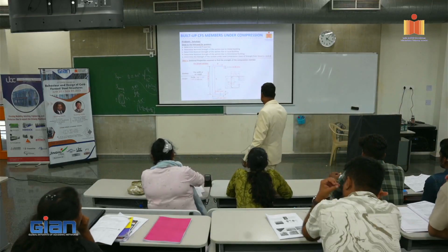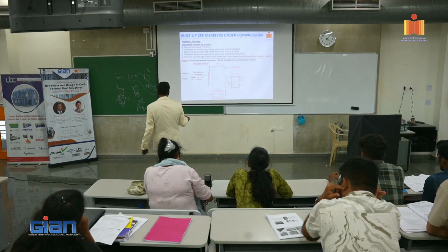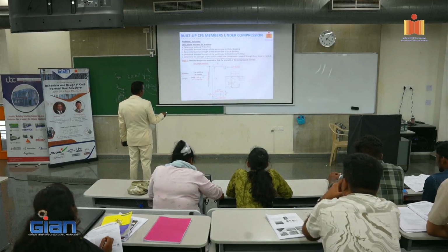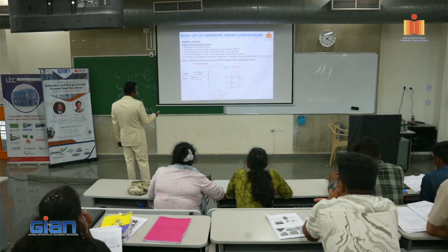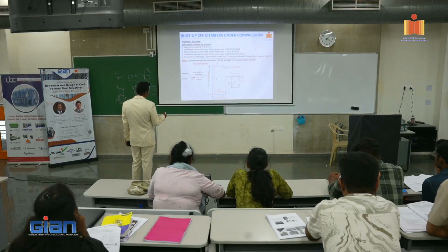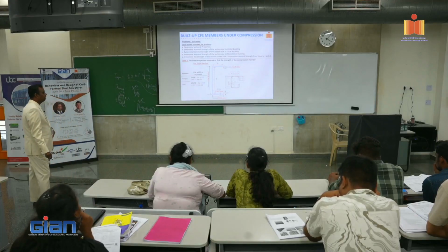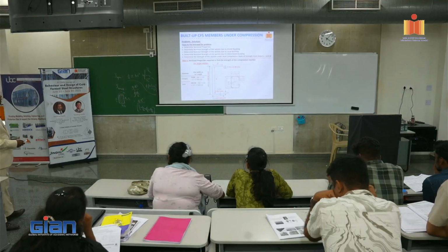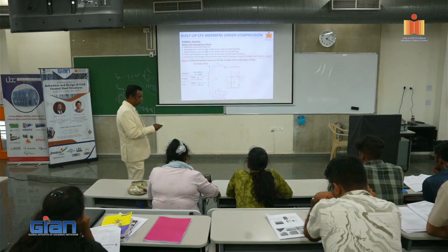So the flange is 74.96, we have 2, right? R plus T by 2, we have to take it out, because the thickness by 2 we have to take it out, so we will get the flat distance. So 74.96 minus 2 into R plus T by 2 is 67.12, right? Next, we will also find out web, it is 199.96, again minus 2 into R plus T by 2, it becomes 192.12. Right, that becomes the web.